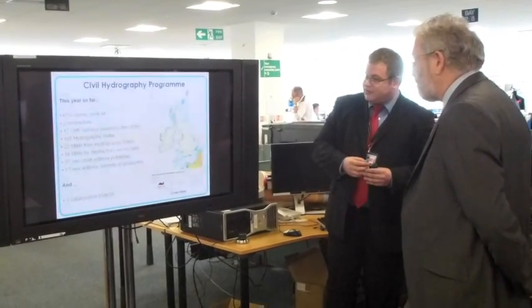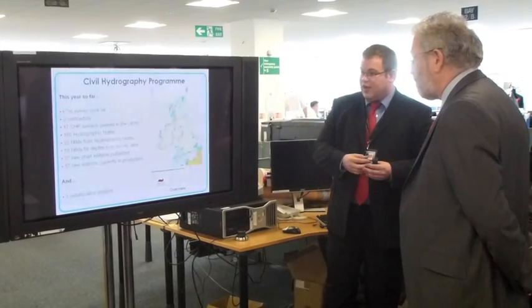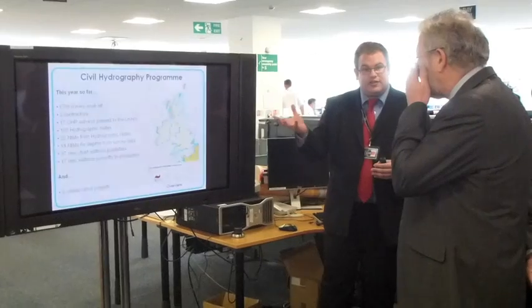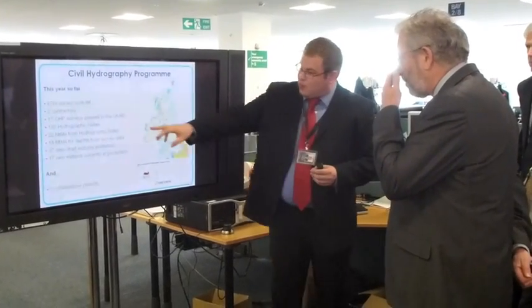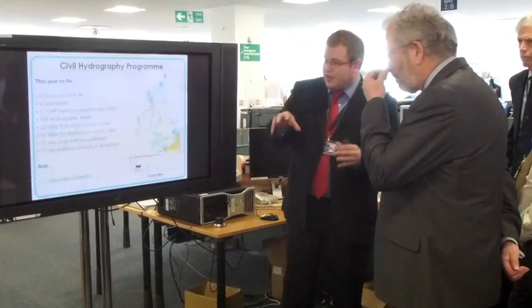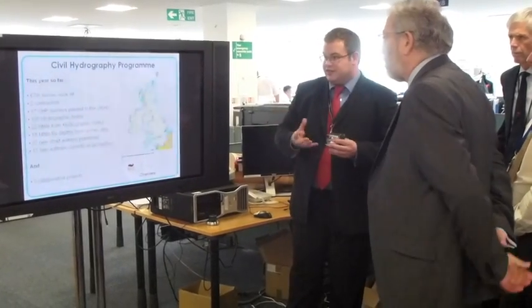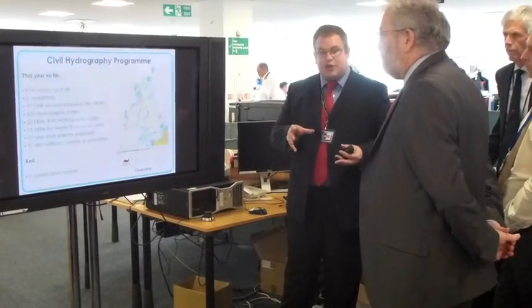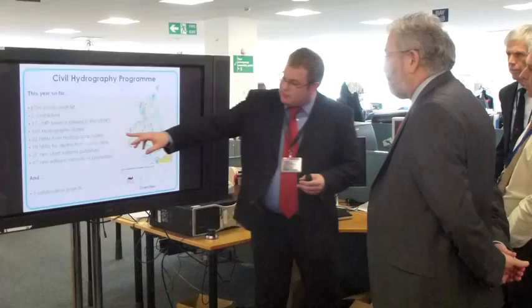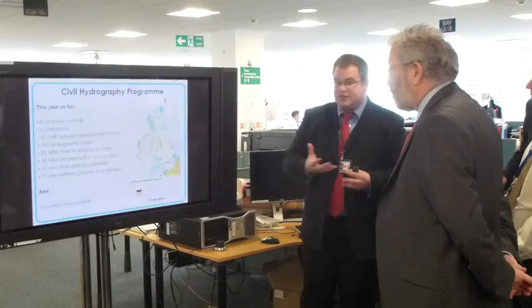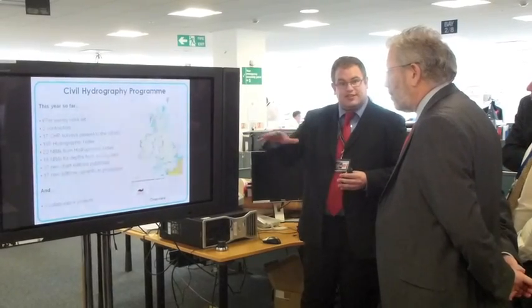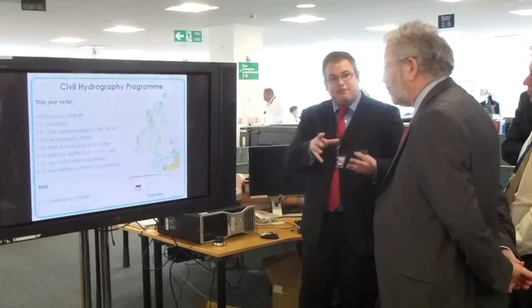So this really tells us that we're getting our prioritisation correct, because if those charts are being updated, then we know that our targeting is working really well, and we're getting reports of hydrographic notes which are features on the seabed that are substantially different from what's charted at the moment. And these have to be sent out to mariners as notice to mariners to advise them that there's a potential issue there with the morphology that exists as being different from what's charted.